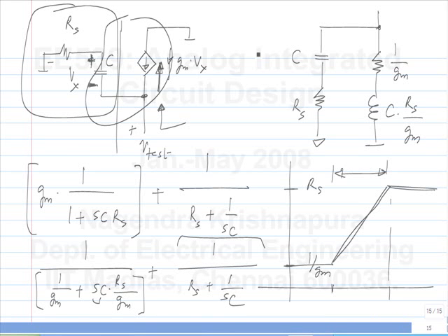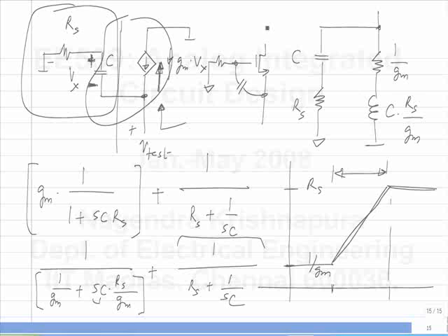This is the small signal equivalent of a transistor, and it will have its own CGS, and you can add some capacitance if you wish. If you put a resistance in series with the gate, it will look like an inductor looking from the source. So this is some circuit technique that is used sometimes. You use inductances to extend the bandwidth. Sometimes because of capacitances you get limited bandwidth. Now you have an inductance, you get a slightly enhanced bandwidth. You can use this active technique. This is an active inductor, one realization of an active inductor. There are many of them.